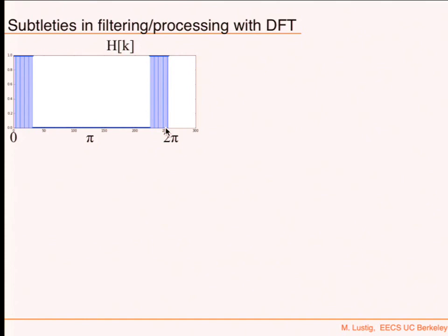First of all, one of the questions there: did I implement an ideal low-pass filter? Because this looks like an ideal one, right? Of course, it doesn't make sense, because an ideal low-pass filter has an infinite impulse response, and this one doesn't. So what the heck am I filtering with? What is the impulse response of this filter?